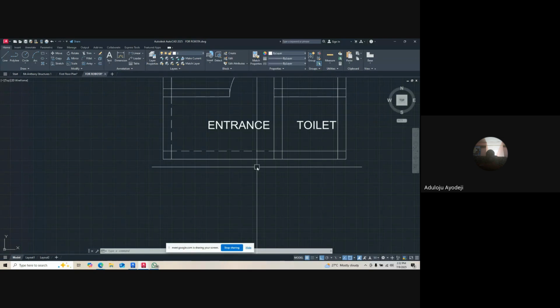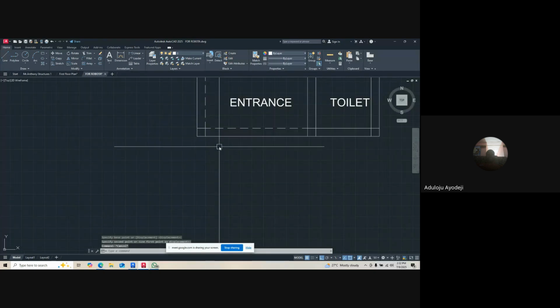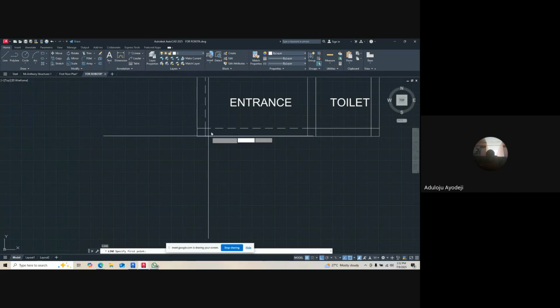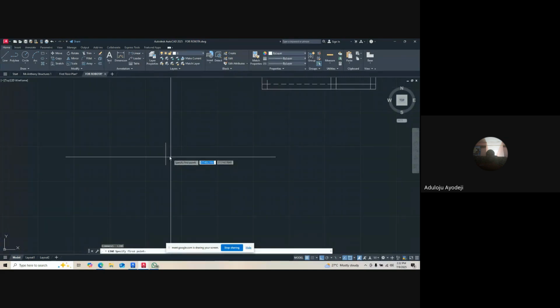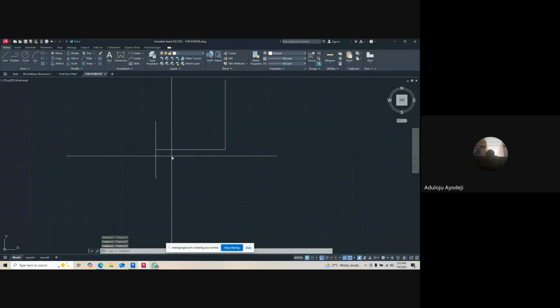And if you want to enter your house, definitely they're going to have a step. And we call something tread and riser. If you can write this thing down, you might think it will not be important, but you'll be needing it. You call something tread and riser. So what is the tread of a step? This might even be one of my assignments I'm going to give to you. So tread is 300. And riser is 150.